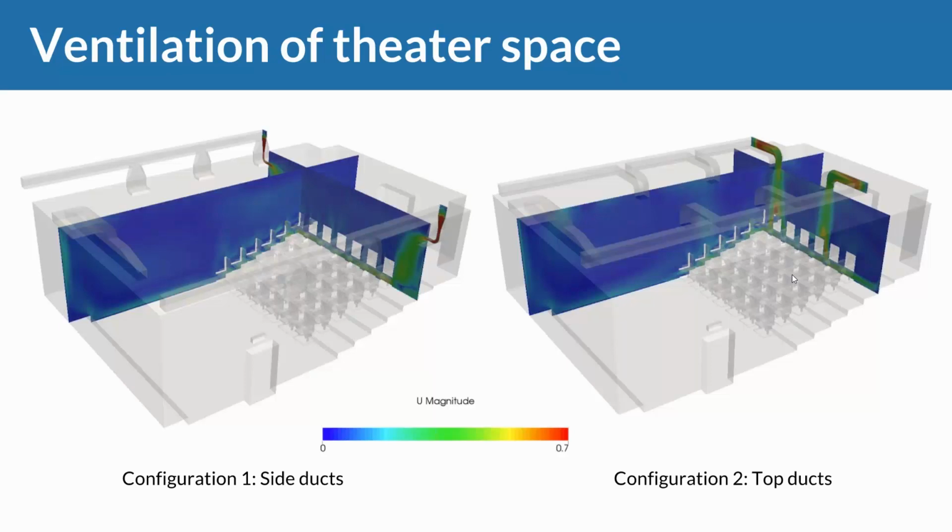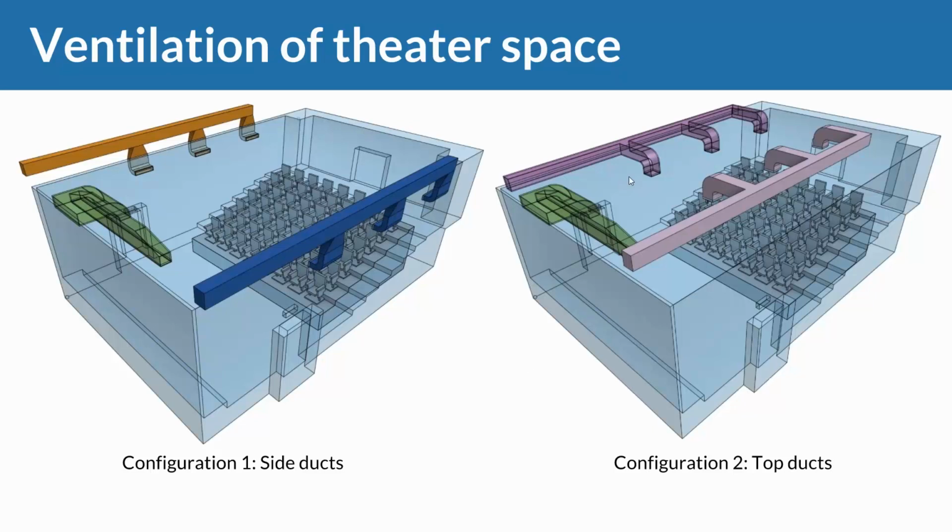And then using a very, very similar process, right? So you would bring in this CAD model, or these two CAD models. You would set up physics such as, okay, I have my inlet air of temperature X, and it comes in with a mass flow of Y, and that's about it, right? And then you're simply bringing in the fresh air.